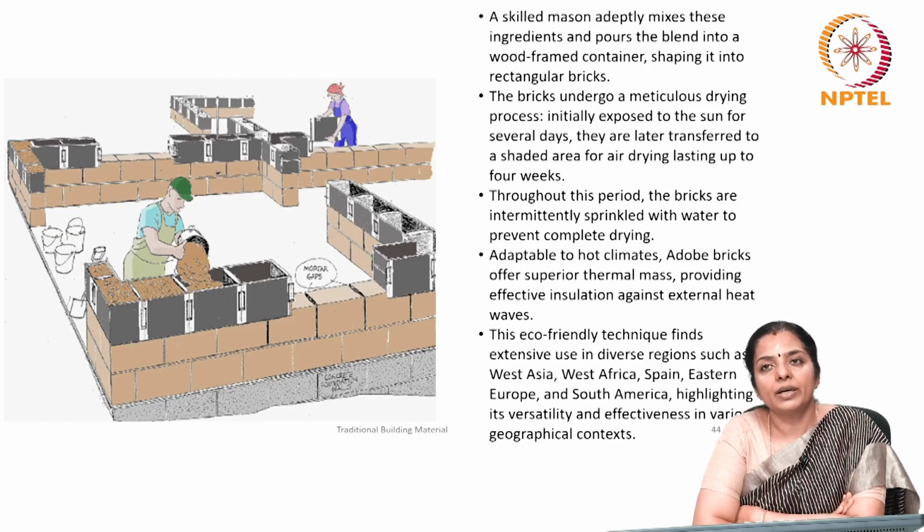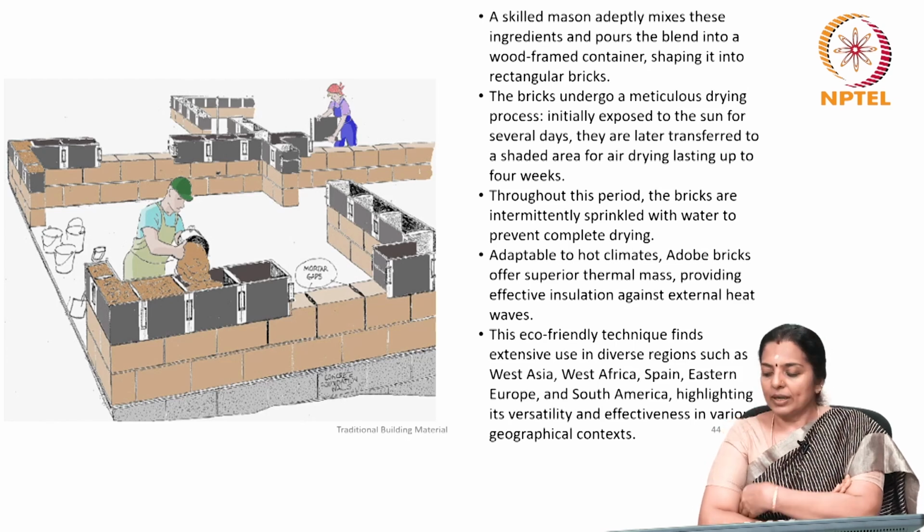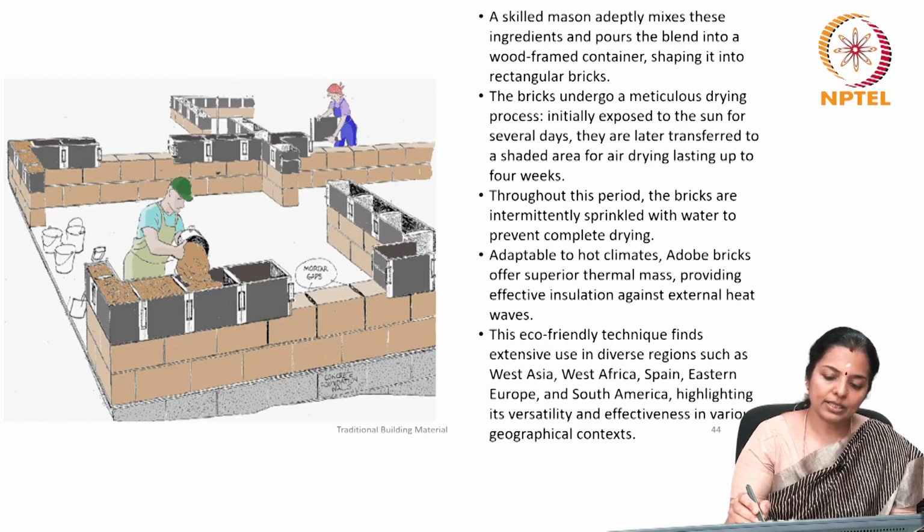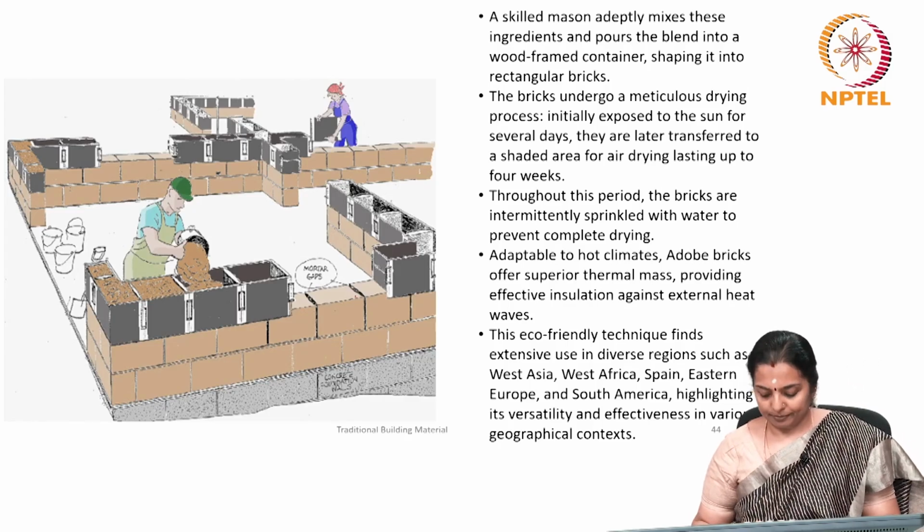And this natural building material doesn't have too many energy intensive materials to be added to it. You can add some organic elements like straw or hay, and clay can be added. You have to be careful about the sand content and water. For better strength, you can add cement and lime. And then you can see from this picture how these blocks can be arranged.